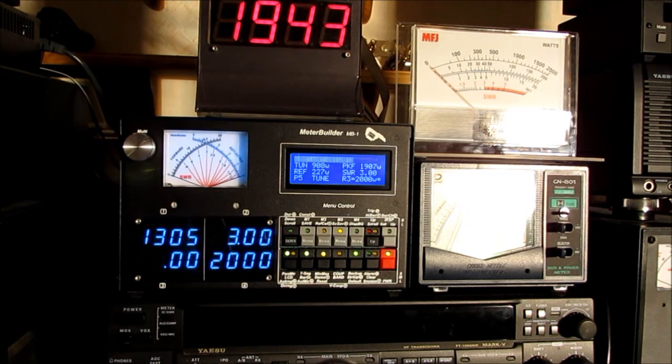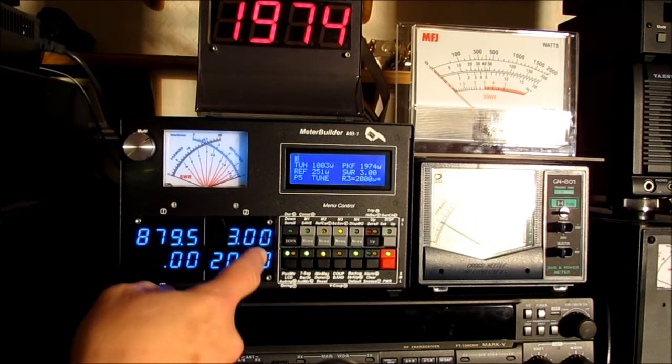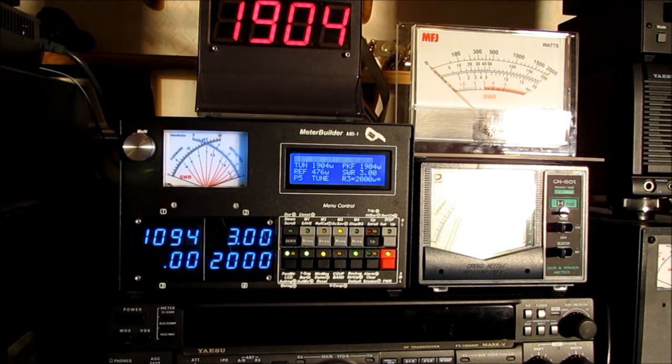It's pretty versatile in the respect that if you have a station that's not located next to the meter head, you can locate your panel meter up to 150 feet away from the meter head, and that could come in handy depending upon your particular configuration. The soft overrange that we mentioned before is particularly useful if you remote an analog meter away from the control head, because you really won't have visible access to the overrange LED, and having the needle have an excursion beyond the full-scale value can be useful in a situation like that. So that's the rundown on the panel meter.